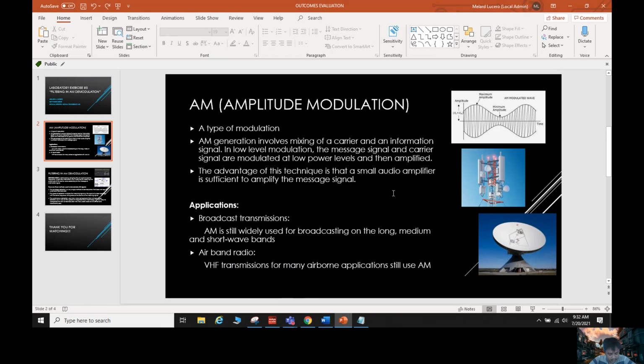So okay, because the standard method produces sidebands on either side of the carrier frequency, single sideband modulation uses a bandpass filter to eliminate one of the sidebands and possibly the carrier signal, which improves the ratio of message power to the transmission power, reduces power handling requirements of line repeaters, and permits better bandwidth utilization of the transmission medium. So some popular applications of this are